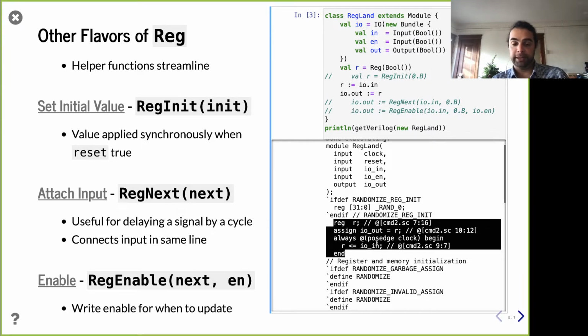Well, we have a register, right? One of the things that drives me bad about Verilog is they have this keyword reg, which you might think means register. That would be a very reasonable assumption. It does not mean that. It's just another language construct. Depending on how it's used and how the CAD tools interpret it, it may or may not turn into a register.